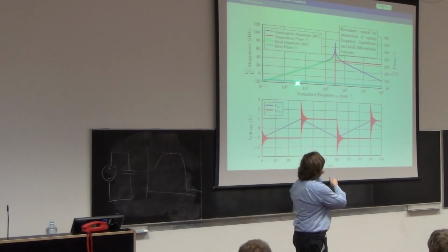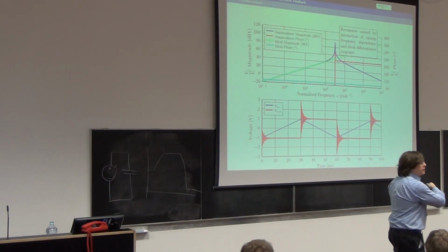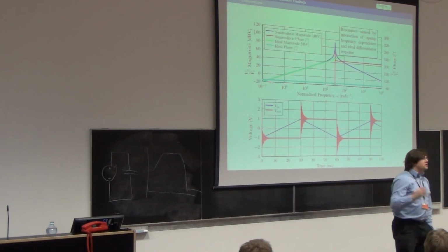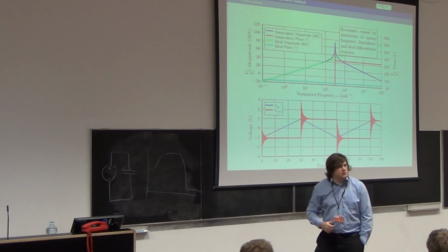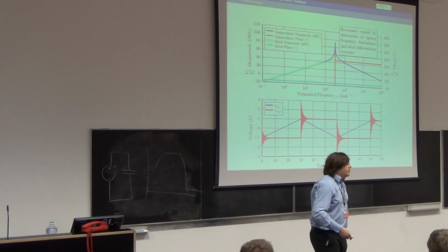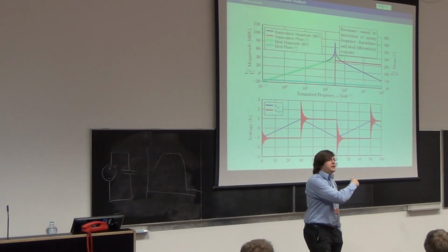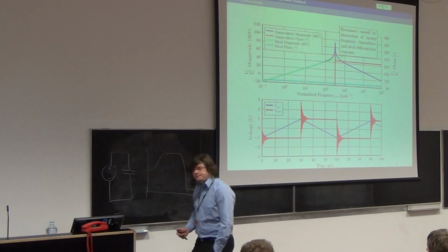And the trouble is, its gain is getting bigger as we go up in frequency. So where there is more noise power available, it has got the biggest gain. It's not its fault that it's noisy, it's just how it is. So people go, oh, differentiators are very noisy. They are, but they're no more noisy than any other circuit that has an increase in gain at higher frequencies. It's just one of those things.